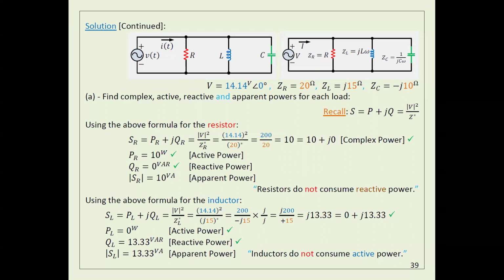It doesn't make any sense to convert an impedance that has j and a real value to the time domain. In our case, the impedance has to be in the complex domain. Why? Because the real part gives you the amount of resistance you have, and the imaginary part tells you the amount of capacitance and inductance you have. It doesn't make any sense to transfer it.